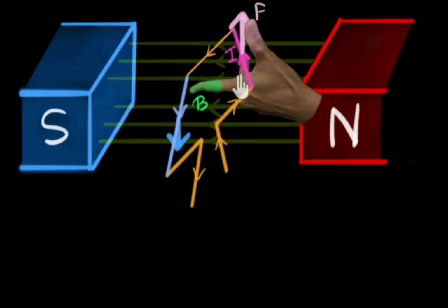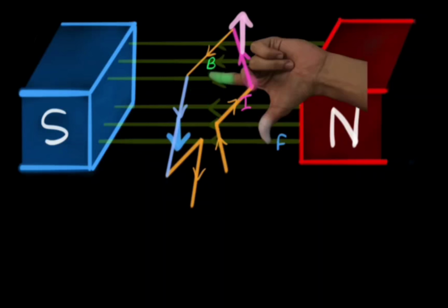That means a sinusoidal wave shape is produced by the conductor rotating in a theoretically uniform field, in which the air gap is not constant because of the straight pole sides. If the pole tips are shaped so that the pole face produces a uniform gap and flux density except in the inner polar regions, the wave shape of the induced EMF tends to be flat topped.